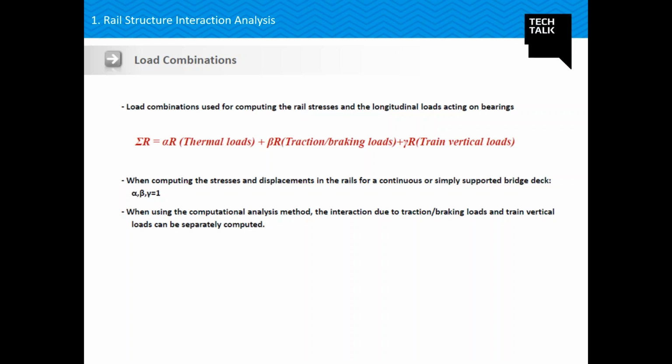It can be easily imagined. Imagine a book kept on a table, and if you try to move that book, you can easily move it. But if you keep a very heavy load on that book and now try to move it, it will be difficult to move. If we draw an analogy, here if my rails are loaded, the stiffness increases to 50 kilonewton per meter square, and if it is unloaded, the stiffness is 25 kilonewton per meter square.